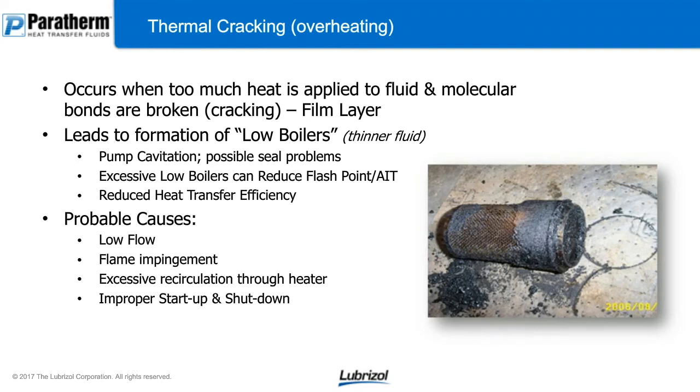So what are your probable causes? Low flow, we talked about that. Flame impingement, where the flame is on one side of the heater more than the other. Excessive recirculation through the heater, and improper startup and shutdown. And that's really influenced by flow more than anything else.